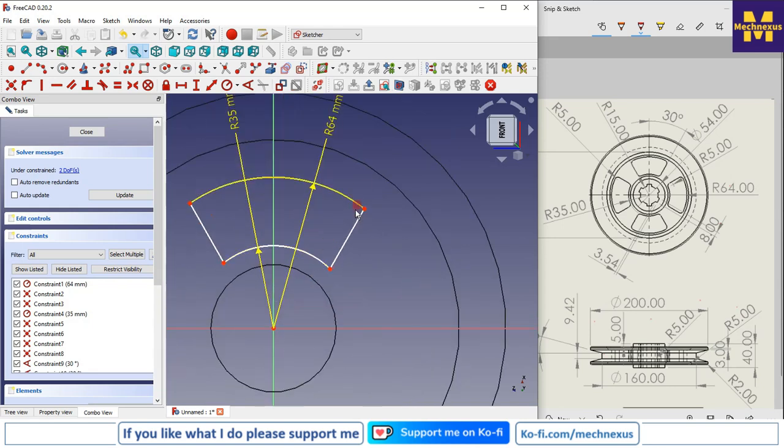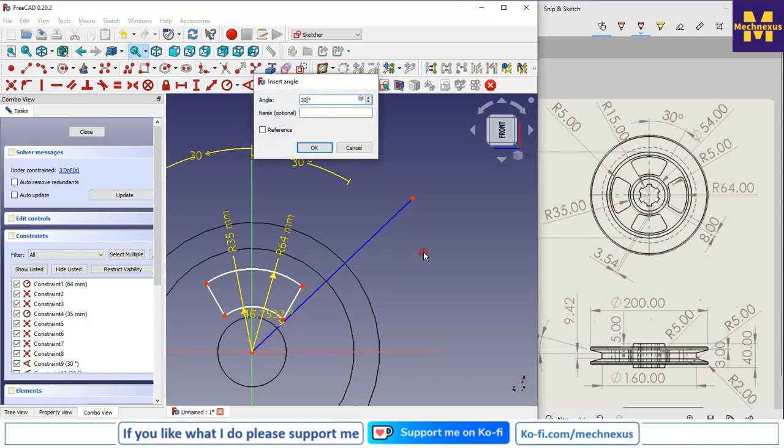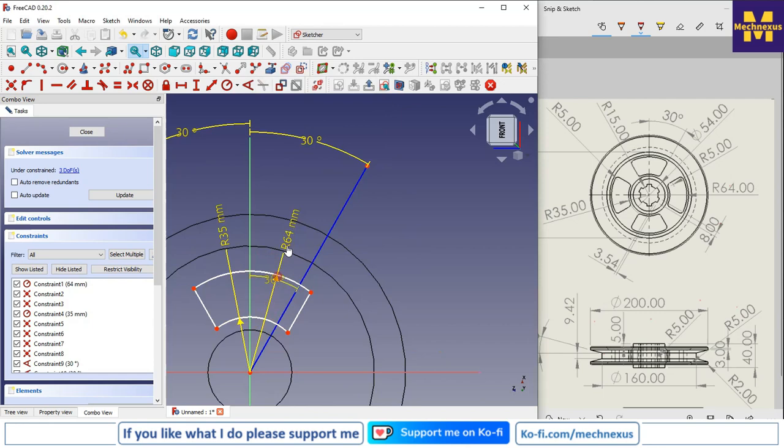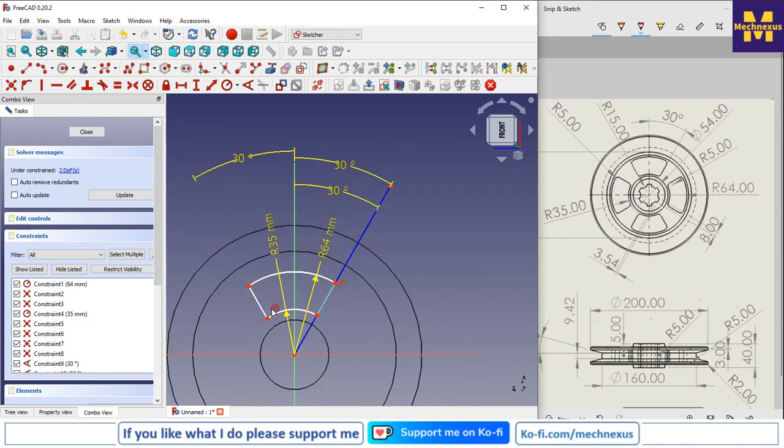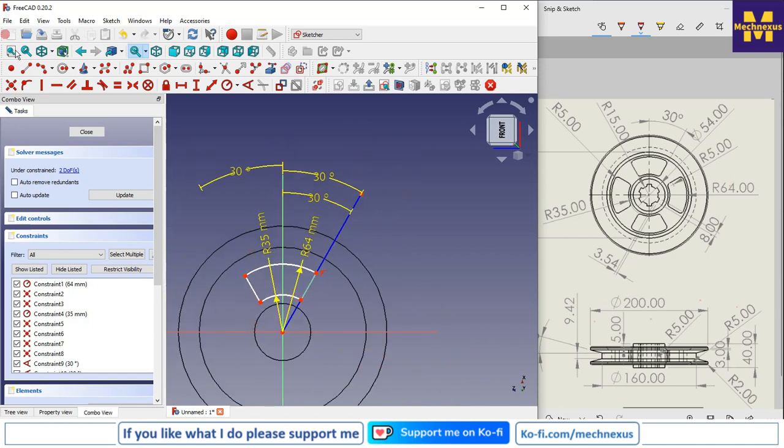So for this, let's draw the construction line, and I will make it a construction, and I will give it an angle of 30 degree. And I will make this and this collinear, so I will select this point and this line and make it a coincidence. So this first angle which you have given has no meaning, but keep it.